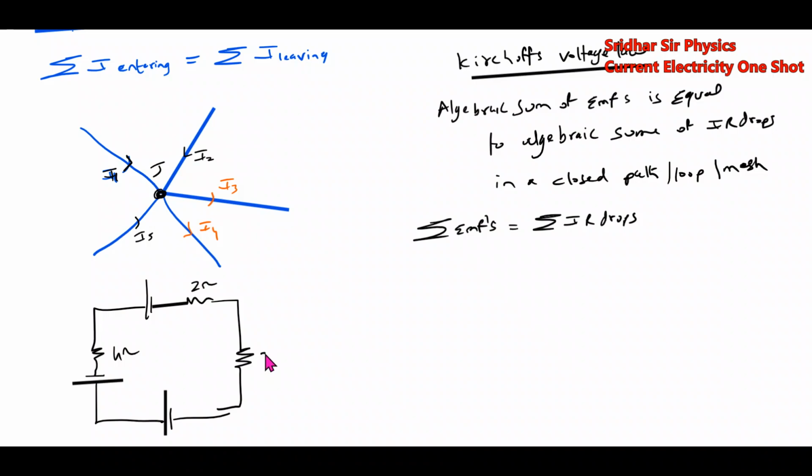2 ohm, 4 ohm, 6 ohm, 4 volt. Then, what about the current flowing in the circuit? How to find that? So we'll assume the current flows in this direction, according to the convention where current enters positive and leaves negative across the resistor, because current flows from higher to lower potential. Based on that, the polarity. So current I will then traverse the loop.